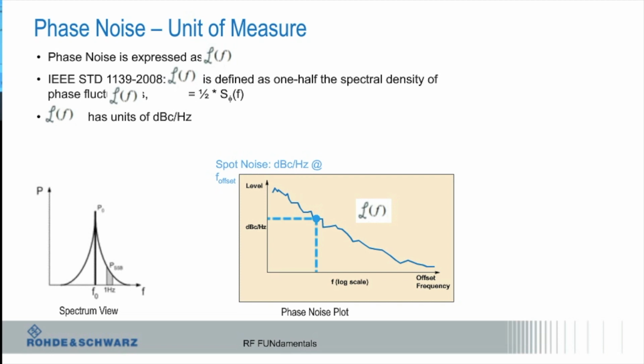Question? Could you think of it in terms of your clock being 10 ppm, and for 1 megahertz, doesn't that translate to the same thing? You're absolutely right. So 10 ppm would be 10 hertz wide on that. Yeah, in terms of ppm. Thank you, that's a good point.